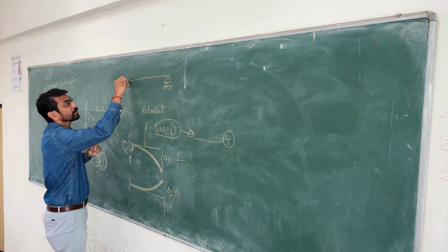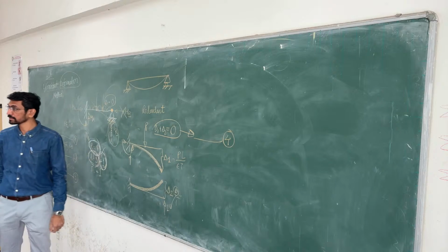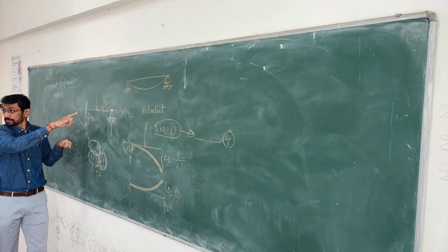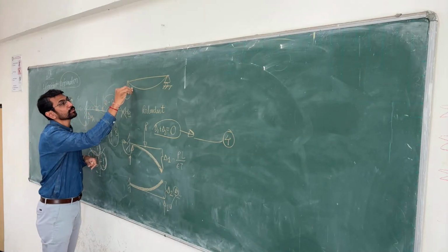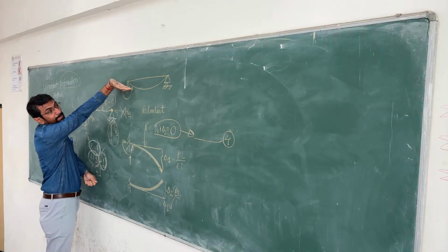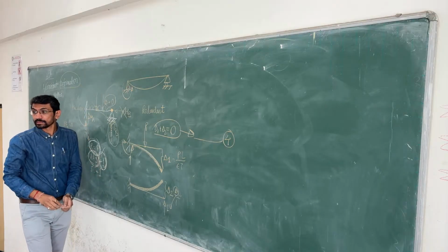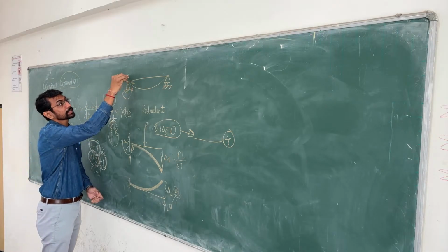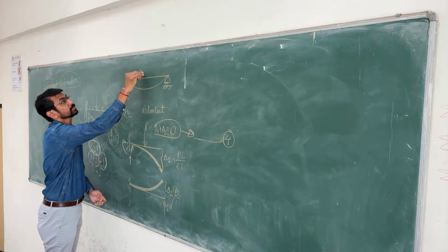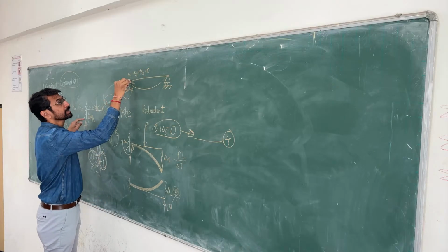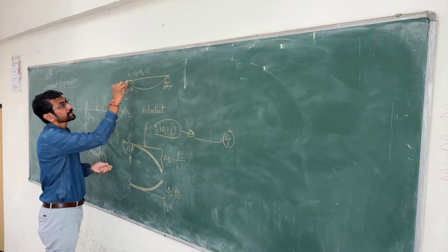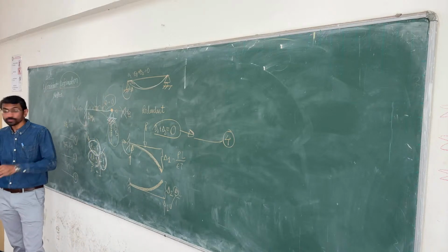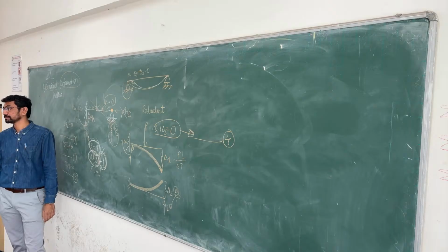तो इसका डिफ्लेक्शन क्या होगा? करेक्ट. नाउ एक्चुअल बीम में क्या है? MN in this direction, right? So you give unit moment to push this beam back to its original position, right? Calculate theta. So in this case there was some theta 1. In this case calculate theta 2. Theta 1 plus theta 2 equals to 0 because fixity पे theta नहीं होगा. इसका एक्चुअल डिफ्लेक्शन ऐसा है. There is no theta here, right? So you can use this method also, whichever is convenient.